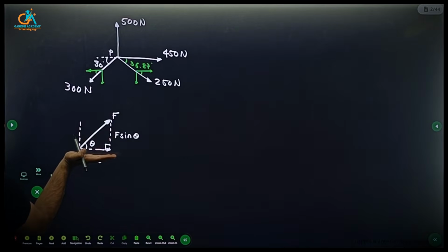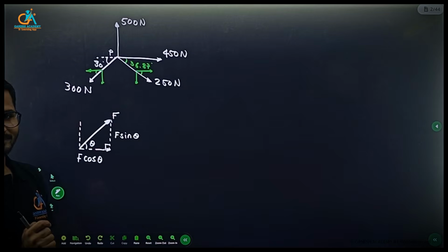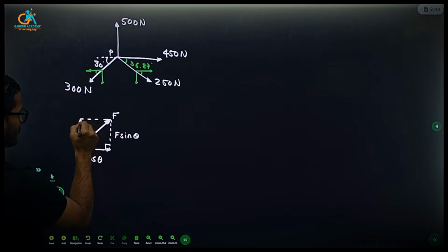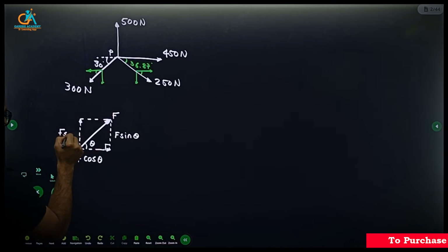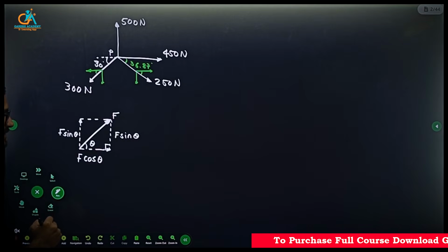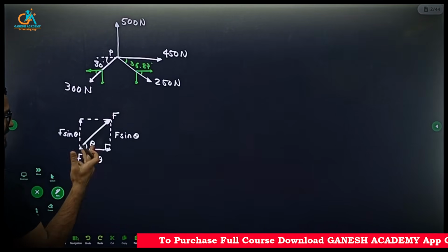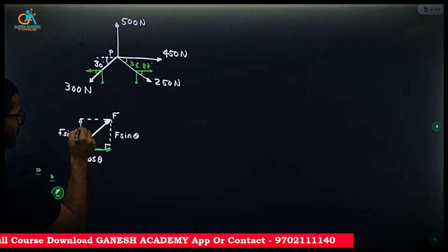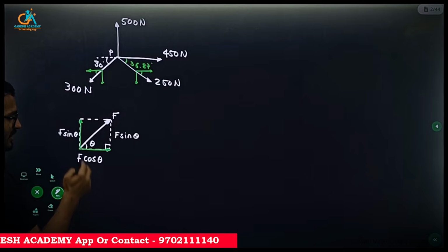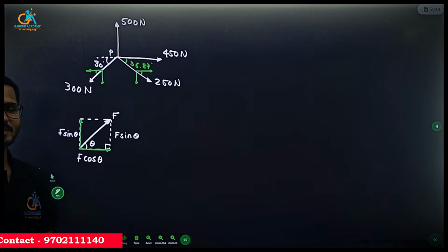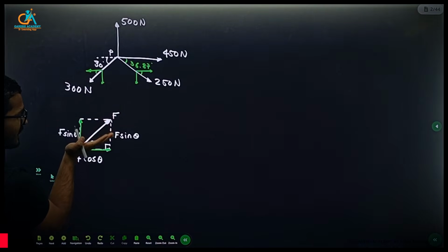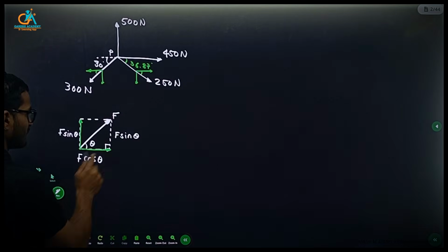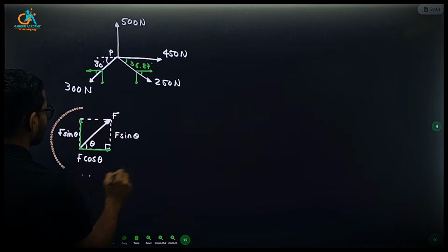So adjacent to the angle will be your cos component, and this is same, right. So this force is equal to F sin theta, right? That simply means we can resolve the given force into components. One is cos component, one is sin component. Remember that cos component will be the force component which is always adjacent to the angle. Okay, so this is the basic resolution of forces.